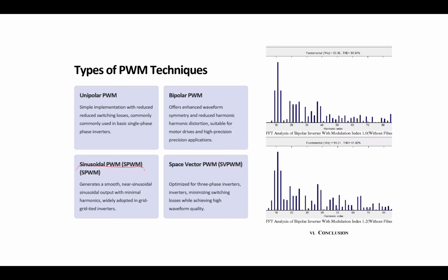So you have three parameters in a sinusoidal function: magnitude, frequency, and initial phase. You change those three in order to control your reference. So in SPWM, we can't just put in any arbitrary reference signal. It's always a sinusoidal, but you can play dynamically with the amplitude, frequency, and phase. Are we good?